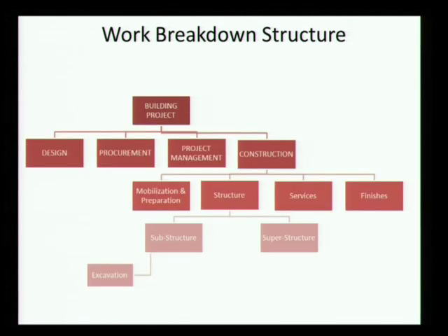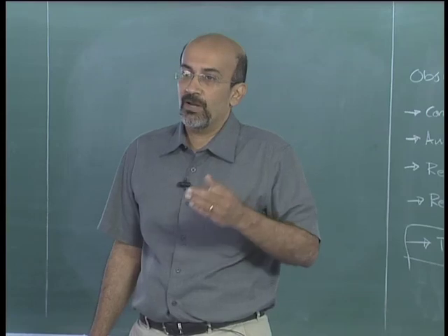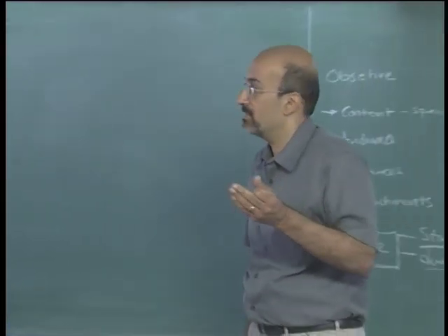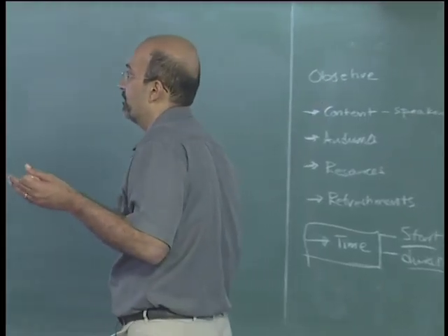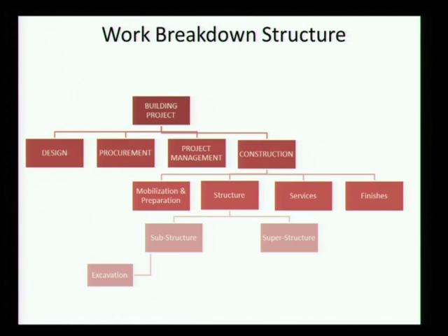Okay, now a similar structure can be taken for a building project. So here I have taken a building and I have broken it into, in the first part, the phases of a building project. Remember, we looked at different phases of a project, design, we looked at pre-design phase also, but here I have taken the initial part and broken into phases. You have design, your procurement, your project management, construction. I have taken construction and then broken it, divided it. I have taken the structure and again started dividing it. So this is a work breakdown structure.